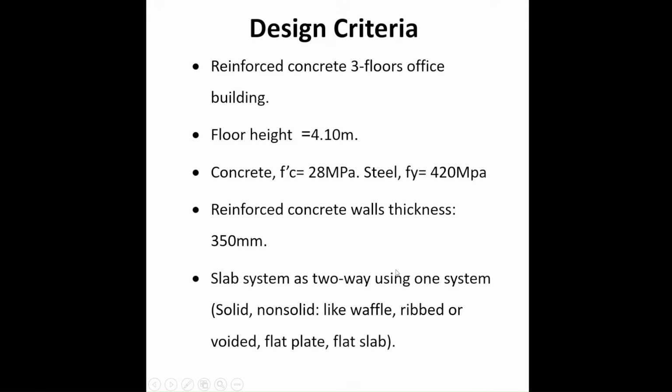Again, for now we are going to talk about the design criteria for this project. Reinforced concrete 3 floors office. So this is our building that we are gonna build and design in ETABS. The floor height each is 4.1 meter. So we have 3 floors of 4.1 floor height.